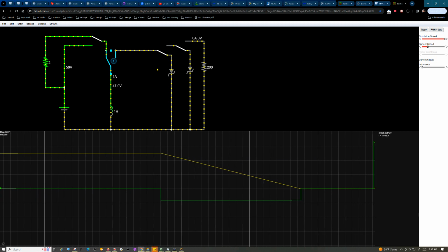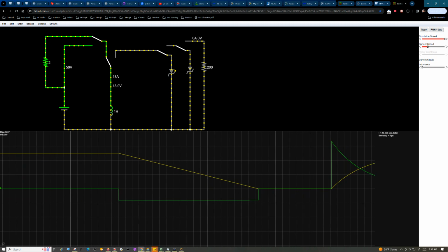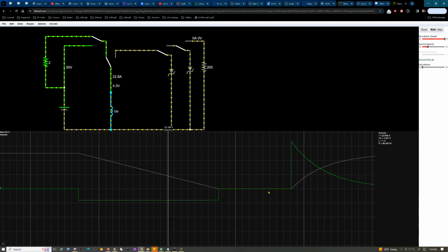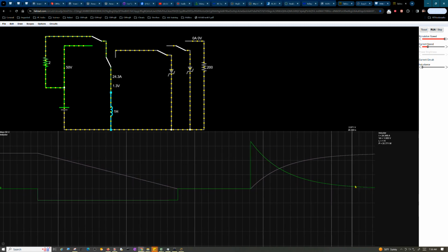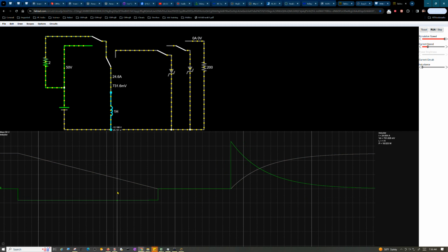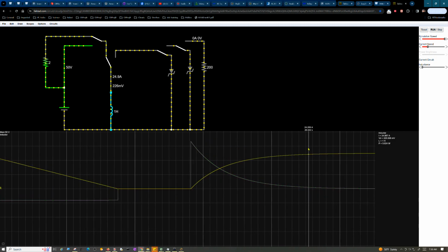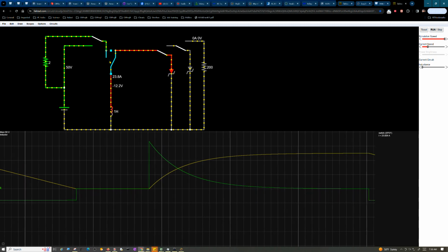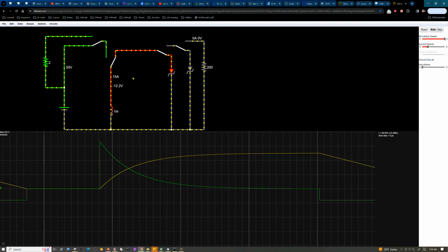So let's go ahead and charge that back up again, but like I said, it still took longer to discharge it than to charge it, as you can see here. Because it's essentially fully charged here. But we charged it at 50 volts, and because it went through a resistor, it takes a lot longer to charge it than it would if we charged it with no resistor. And I'll do that next just to show you.